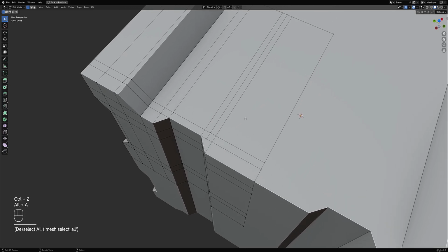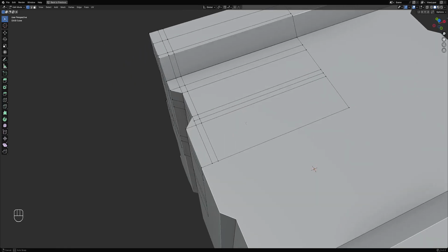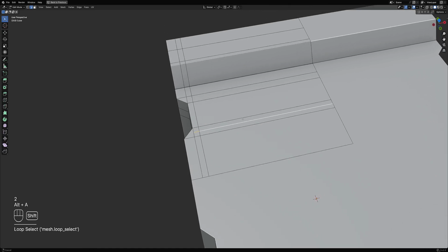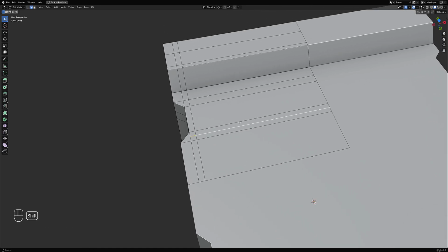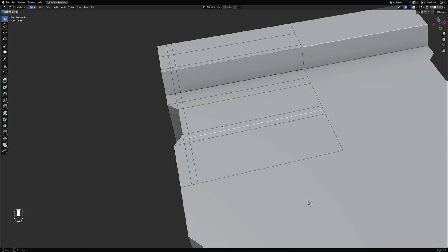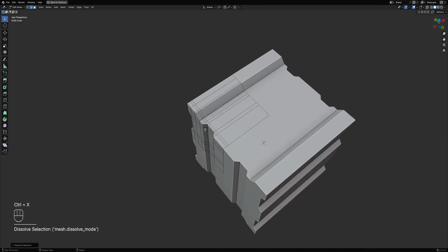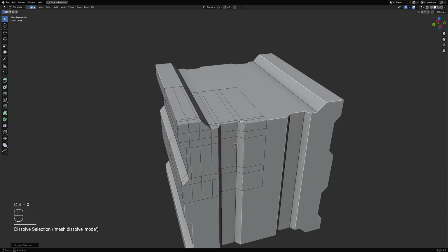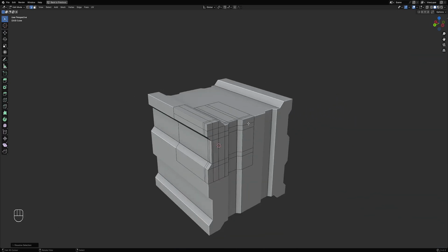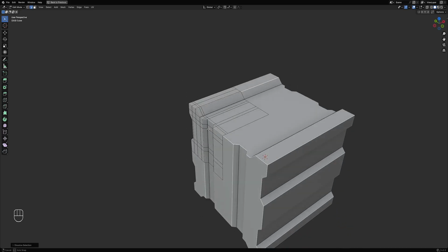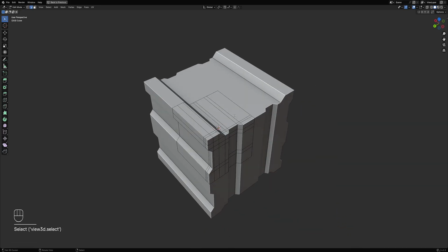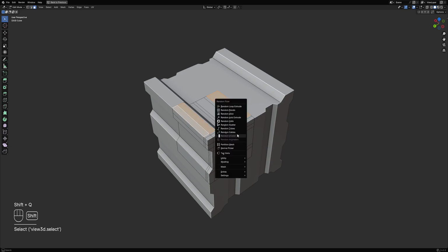It's called a diamond face, from my study in topology days. So you can make this a quad by doing that. Okay, so those are the basics of how to use it: select the faces that have the same planar direction, then use quad slice.